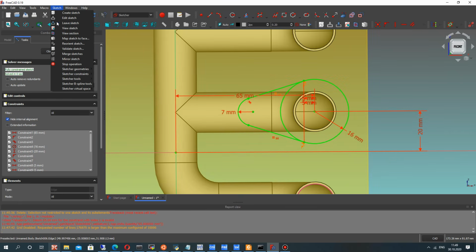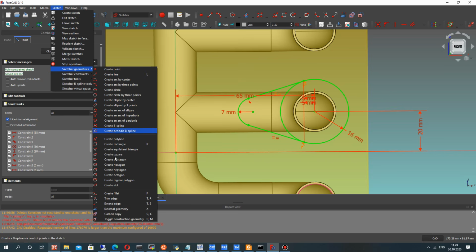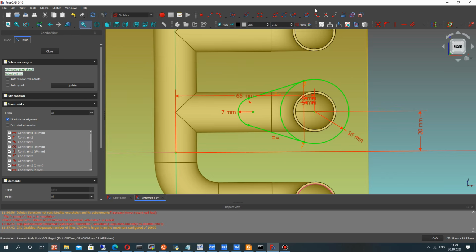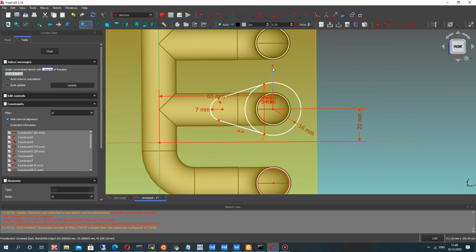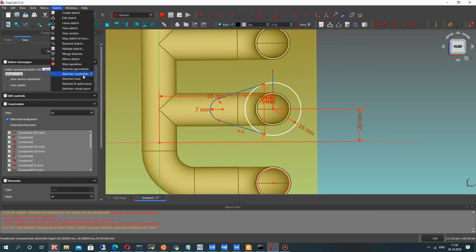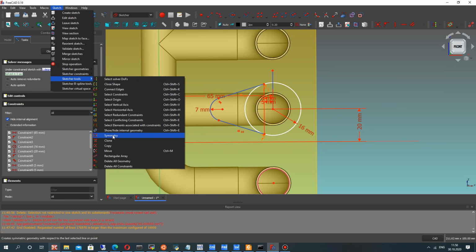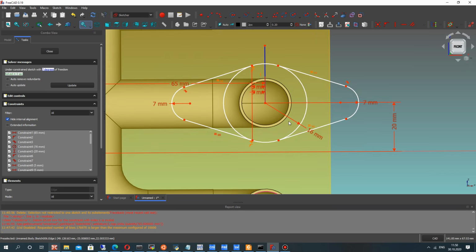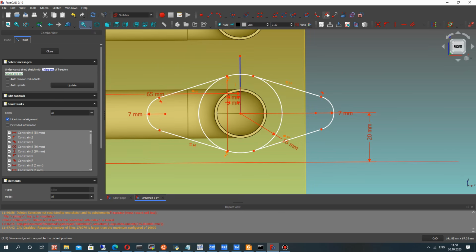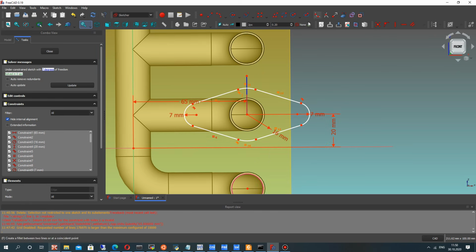And now let's go to the one important thing. Let's choose this toggle constraint. Let's create this blue line. With this blue line, we cannot create some things like with the two other lines. We will use it like axis for symmetry. Let's choose all our lines and create the symmetry. The last line will be this blue line. Okay, and we have the symmetry here, and let's make the trim for circle, and we have here the flange.